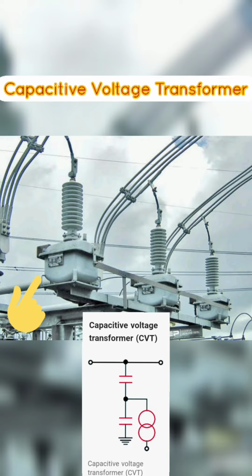In electrical substation diagrams and schematics, capacitive voltage transformers, CVTs, are represented by specific symbols to simplify their identification and interpretation. The commonly used symbol for CVTs is a circle with two curved lines inside, as shown above. The circle in the center represents the high-voltage capacitor, and the two curved lines represent the low-voltage capacitors connected in series or parallel to form the secondary winding. The lines protruding from the symbol represent the connection points for the primary and secondary windings.